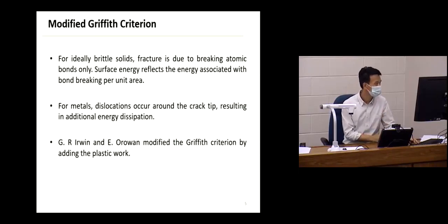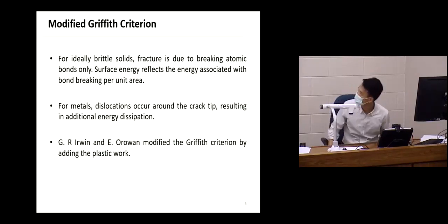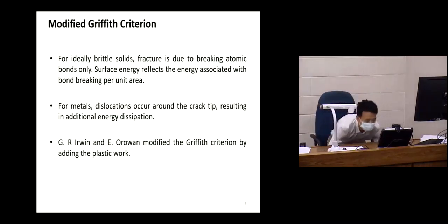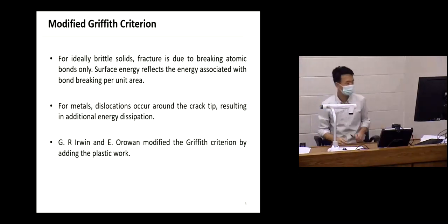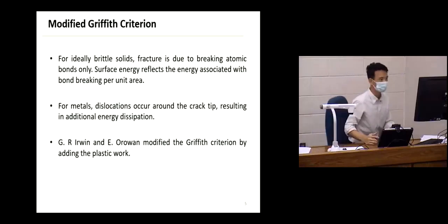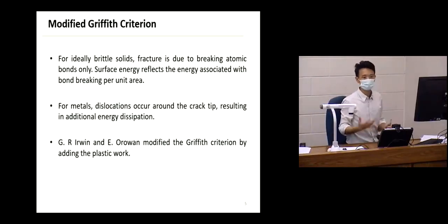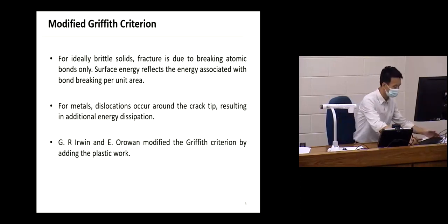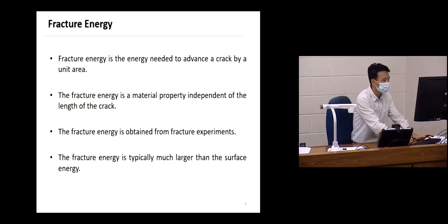So this is a modified Griffith criterion that is proposed by Irwin and Orowan. Okay, so the modification is quite simple, right? I know there's surface energy that is associated with actually breaking the surface, but before I actually break the surface, there's also energy going into plastic deformation. So I just need to account for both of these. So the final modification that we need is to